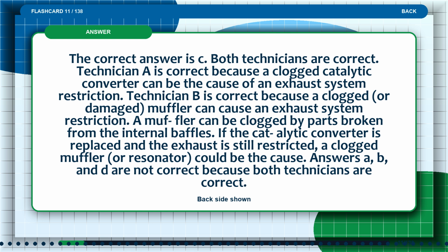If the catalytic converter is replaced and the exhaust is still restricted, a clogged muffler or resonator could be the cause. Answers A, B, and D are not correct because both technicians are correct.